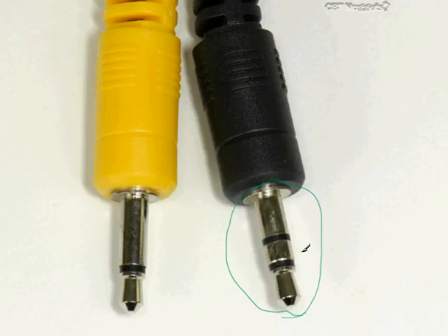And I can tell you're going to get stereo because it uses two rings right here on this 1/8" jack. Anytime you see two black rings like that, or two ringed areas, that means that it's going to be available in stereo, meaning that it comes out of the left and right speakers independently. Whereas this would be a mono 1/8" jack, and you would get the same sound out of both speakers instead of different sound independently out of each speaker.